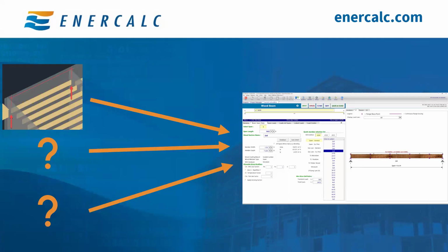And of course, as part of that first category, you also need loading information. Loads can come either from the Revit model or they can be inserted in the ENERCALC interface, just like you would for a conventional manually built calculation. That's pretty much just a matter of taste and workflow preference, whether you create those loads in Revit or whether you create them in ENERCALC. And we're going to look a little bit at both of those options.